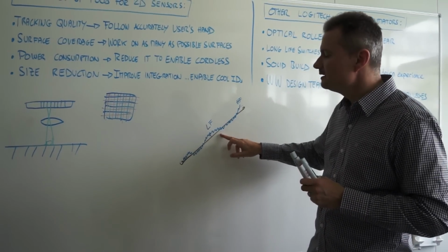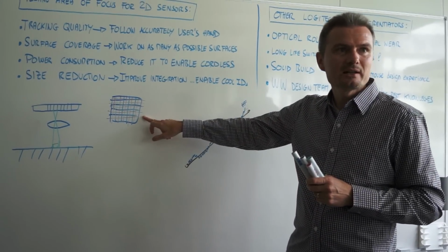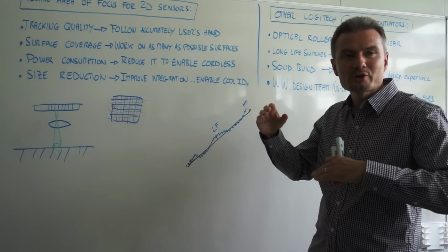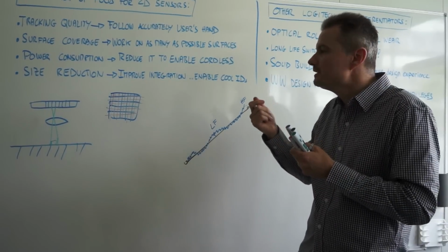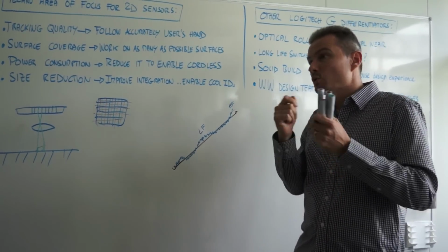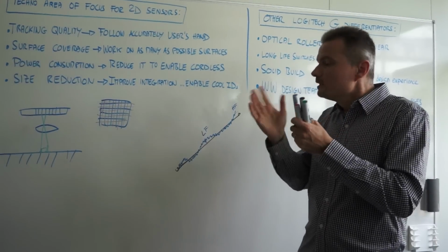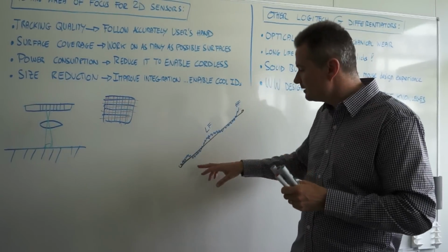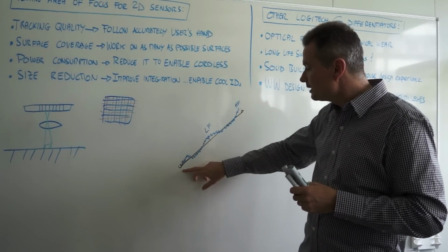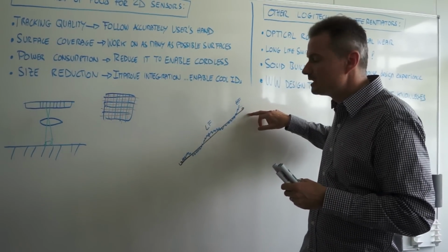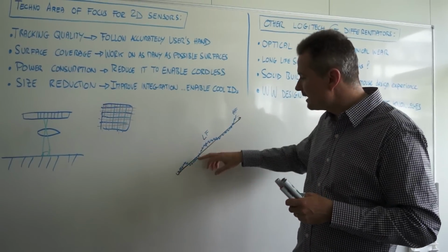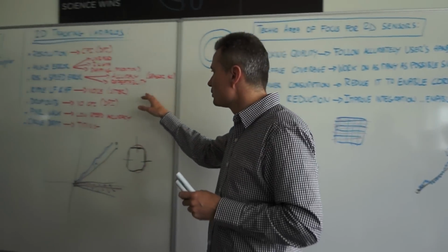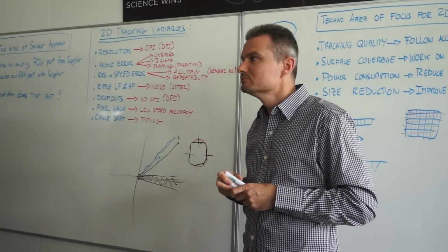And this is clearly coming from that. The more you raise the DPI, the more you have this problem. Because it's natural. You have a problem with the noise floor, you have less dynamic, you have less capability of the sensor to identify what is real motion and what is wrong motion, and your system is hesitating. And sometimes it believes, okay, it's tracking, no, yes, no, and then it creates this variation, because the ideal trajectory is there and is capable of seeing it. But if you ask too much DPI, you will end up with something like this, very nervous and very unpredictable. So this is what we call ripple. Any question on it? No.